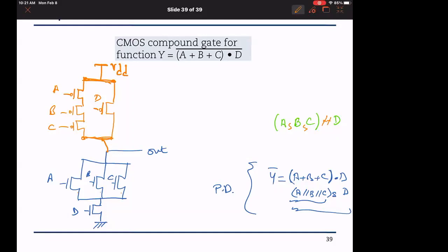It will start from the logical or behavioral level. We divide it into logical units, and then for those logical units, the technology now is tending to go to more regularized small designs. The more the fabric is made from small and compact and well-known gates, the better it is. So this is called synthesis, logic synthesis. I have a logical function and I need to synthesize it into gates. So I need to know which gates I pick. Sometimes we have a pool or a library of gates, and sometimes we do custom design.